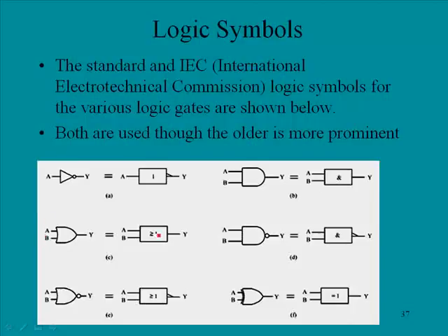If you have one input, then you get an output. Here we have a NOR function, same thing except that you have the slash for the inversion. Then this is obviously an AND gate. This is the AND with inversion, which makes it a NAND. And then equals 1 here would be the exclusive OR, because with exclusive OR, you must have a 0 and a 1 to get an output.